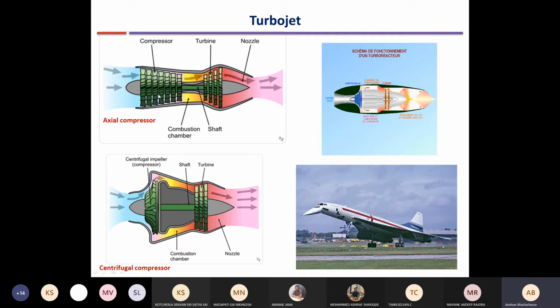And there can be either axial flow compressors like this. Axial flow compressors are like your fans. Okay, the flow comes in axially and goes out in the same axial direction, similar to a fan. So if you consider an exhaust fan, you will see curved blades. You provide some work input to the exhaust fan, right, in terms of electricity. So that actually results in increasing the pressure of the air as it moves from one side to the other. A slight increase occurs. So in the compressor, the blades are more curved and more increase in pressure occurs in each stage. And with multiple stages, you get a large increase in pressure. So there may be 10, 15 stages.